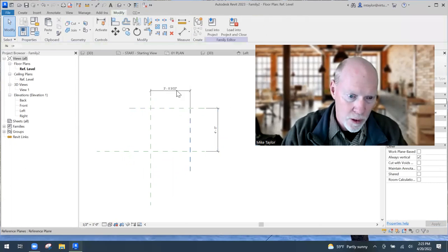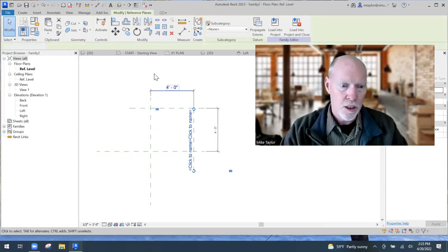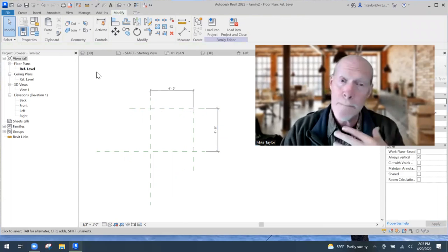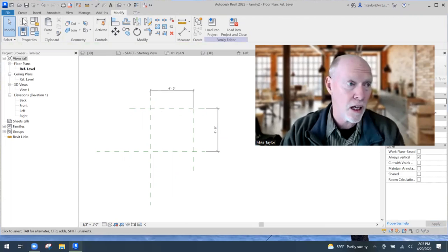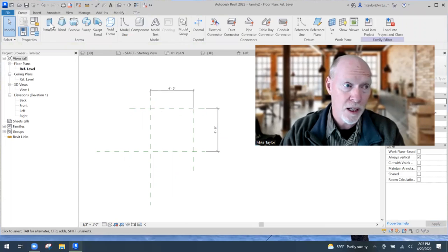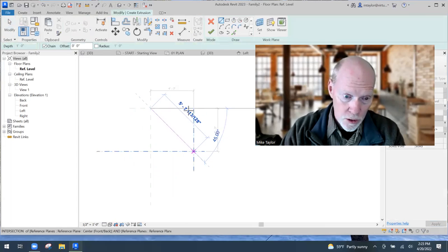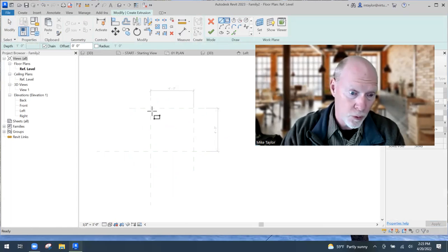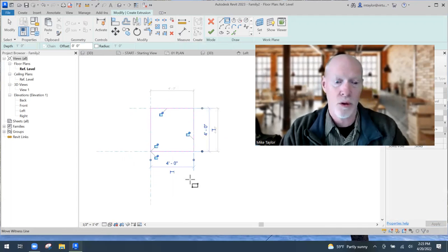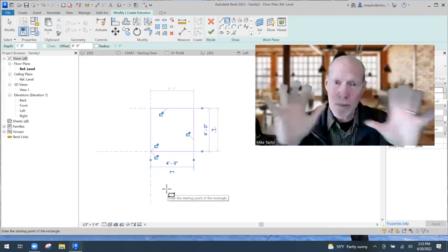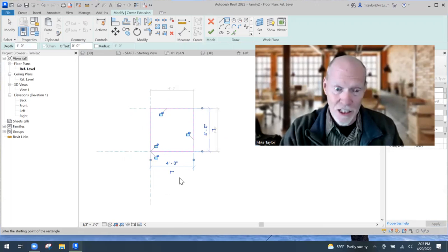And then I click on this one and update it to be 4 feet. So now is when I create my physical solid object. I'm going to hit create, an extrusion. I'm going from this corner. Okay, wait, I want a rectangle. From this corner, I'm putting in a rectangle, from that corner to that corner, okay? And it automatically grabs the corners and locks to them.